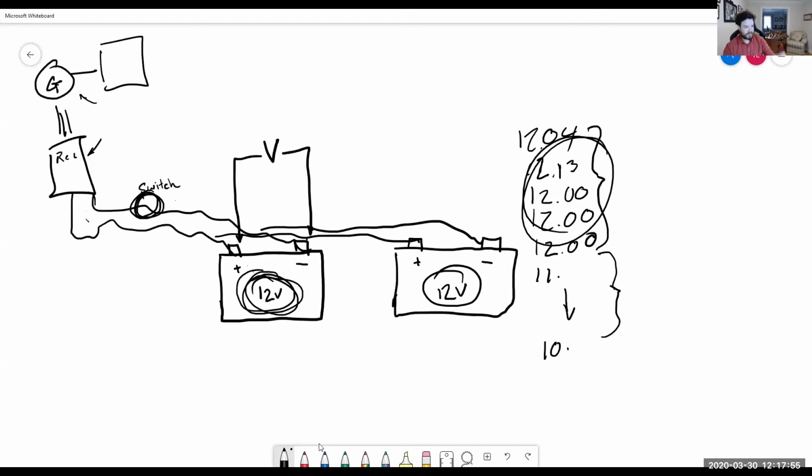So what happens if you have your red probe and your black probe on a voltmeter? Red's usually positive, black is usually your ground. You take your positive lead and put it onto the positive terminal, and your negative ground onto the negative side. So what will you actually get? Say you have a 12 volt reading. Would it be positive or negative?